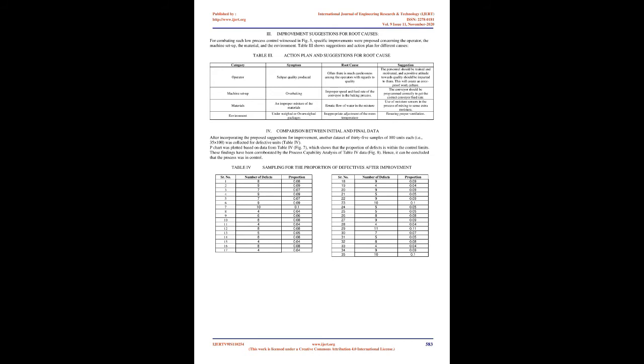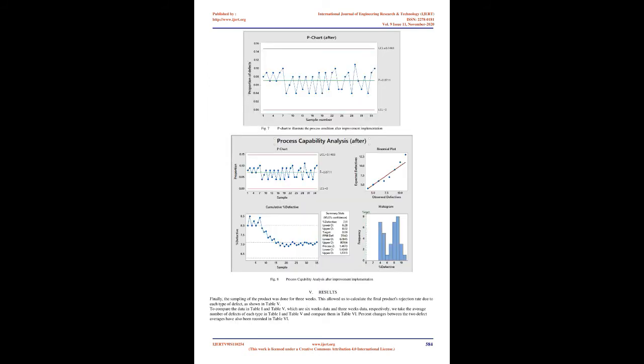Process capability. Process capability indicates how the process can produce items within the control limit. Process capability compares the output of an in-control process to the specification limits by calculating the ratio of the spread between the process specifications to the spread of the process values, as measured by 6 process standard deviation units, also known as the process width 6. Process capability analysis has been done for the data presented in Table 2 using the Minitab toolkit, Fig. 6. Referring to Fig. 5, it is clear that the process is erratically out of control, with 7 data points falling out of the control limits.